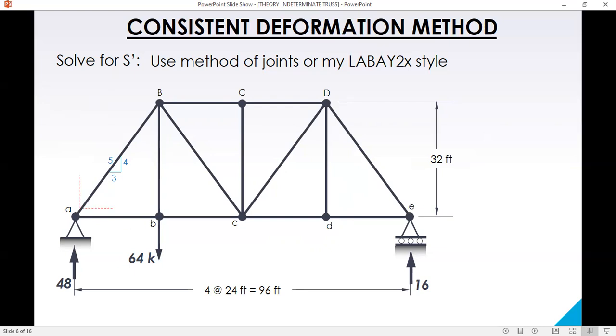Okay. So instead of summing up forces along x and y, let's analyze this one practically. Now, we have 48 kips of force upward. So that the vertical forces become 0, we have to balance this force with this one. Therefore, the value of this component must be 48 also, acting downward, so that the total vertical forces will be equal to 0. So this force must be 48.